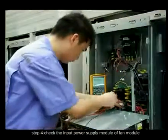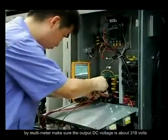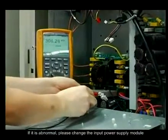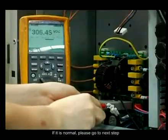If normal, please go to the next step. Step 4. Check the input power supply module of the fan module by multimeter. Make sure the output DC voltage is about 310 volts. If it is abnormal, please change the input power supply module. If it is normal, please go to the next step.